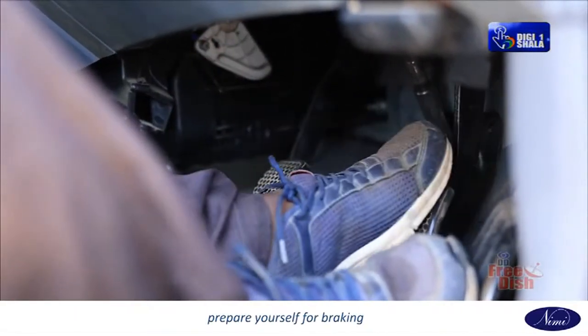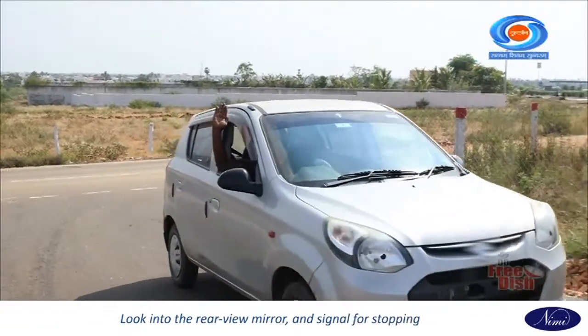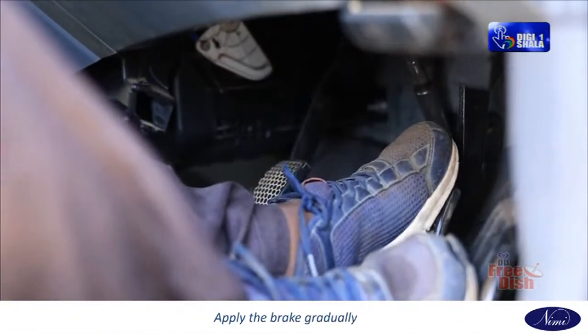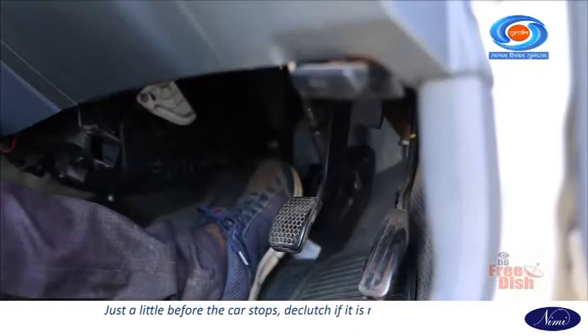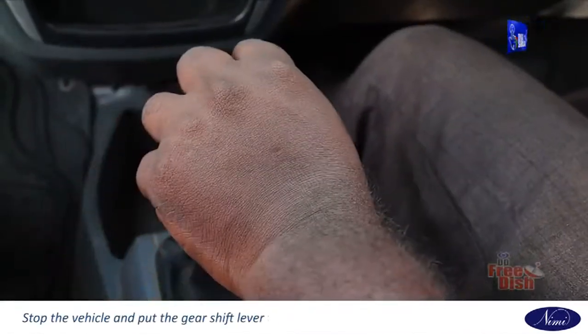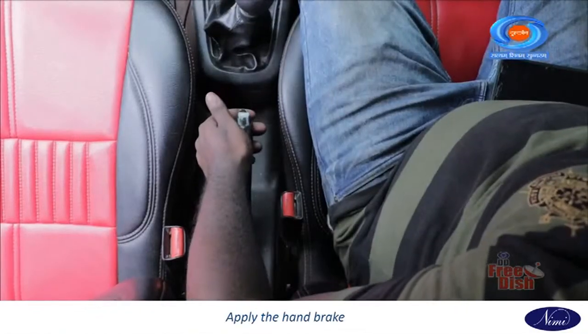Prepare yourself for braking. Look into the rear view mirror and signal for stopping. Release the accelerator pedal gradually to avoid jerky movement. Apply the brake gradually. Just a little before the car stops, declutch. If it is not done properly, the engine will stop running. Stop the vehicle and put the gear shift lever to neutral position. Switch off the ignition. Apply the hand brake.